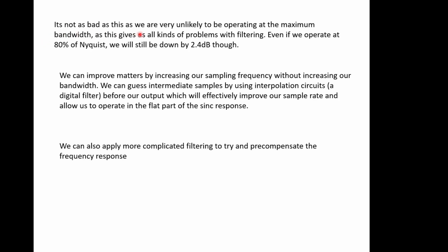It's not as bad as this, as we are very unlikely to be operating at the maximum bandwidth because we've already decided that operating at the Nyquist frequency is not that easy anyway. This is just another problem that we have. So even if you only operate within a fraction of the bandwidth, if you operate at 80% of the Nyquist frequency, for example, you're still going to be down by 2.4 dBs. Remember, 3 dBs is a halving.